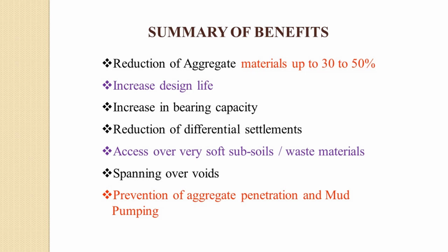Because the aggregates get interlocked with the geosynthetic material. Otherwise, when a moving load is there, there is a bending and releasing action in a flexible pavement, which is not visible to our naked eye. But when they are interlocked, due to bending and motion, the aggregates that would otherwise move apart, as is shown, are prevented from doing so. That means it can stay interlocked for many more million axle cycles than originally. That means the road is not going to fail for more axle loads.